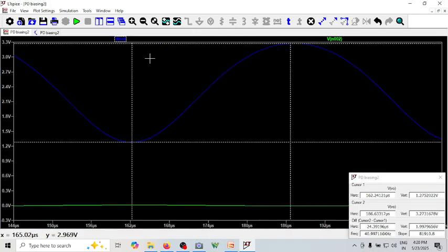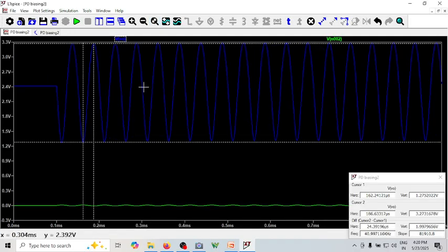Okay, now you can see this is your output. The input is so small. So now you can make out the output is 100 times that of the input. When you're separating it out, almost both of them look similar because this is zoomed out. So that is the gain. The gain is almost 99.5. But how do we theoretically verify that the gain is 99.5?